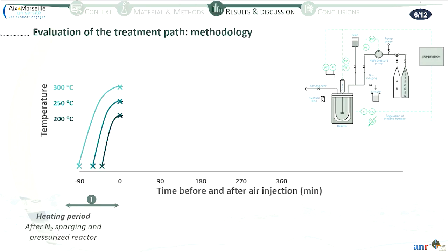So each experiment was separated in 4 steps. We had a first step of heating. So here the duration will depend on the temperature. It's a duration between 40 and 90 minutes for temperatures between 200 and 300 degrees Celsius. This step occurs without oxygen and under a pressurized system with nitrogen.